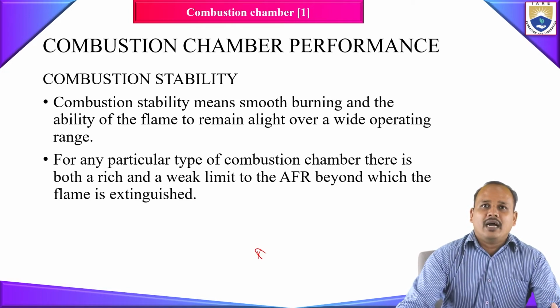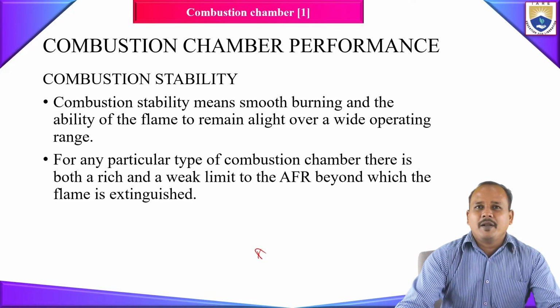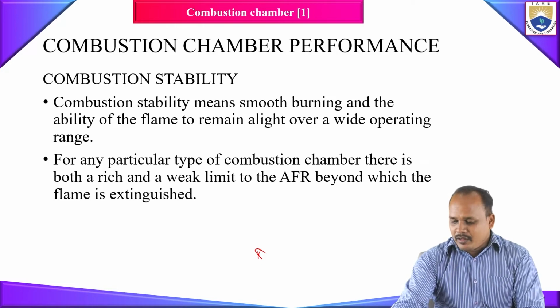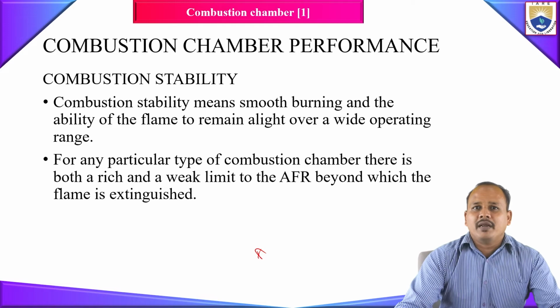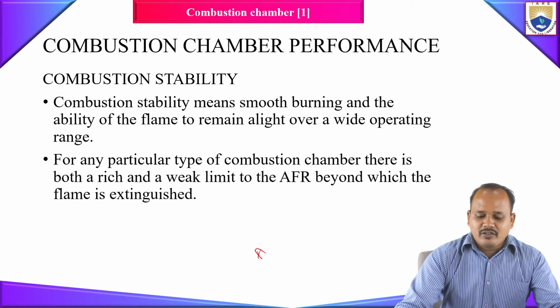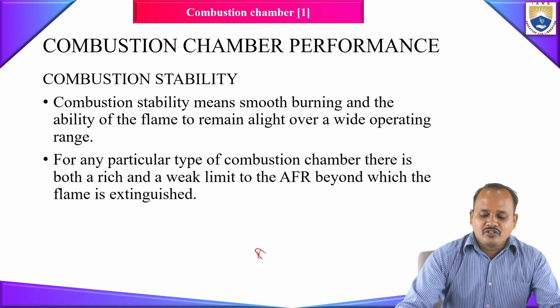If you go beyond that, what will happen? Your combustion process won't be stable. For example, if the air fuel ratio keeps on increasing after a certain limit, what will happen? The air fuel ratio becomes very high, the amount of heat released will be very less, because your airflow is very high, which will lead to extinguishing of your flames. Once your flame is extinguished, you won't have a self-sustained combustion process.